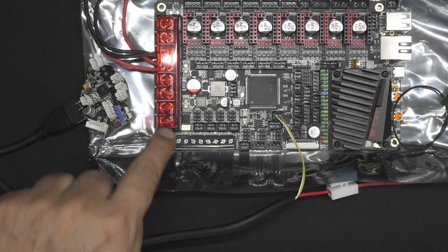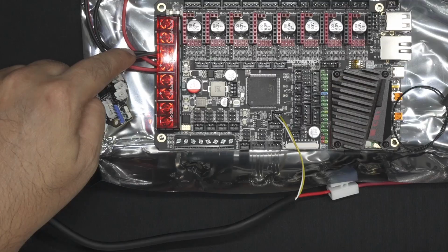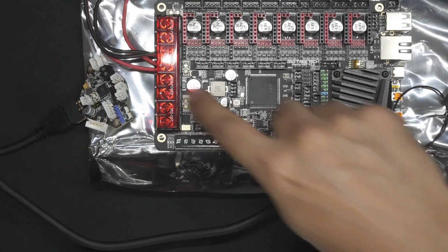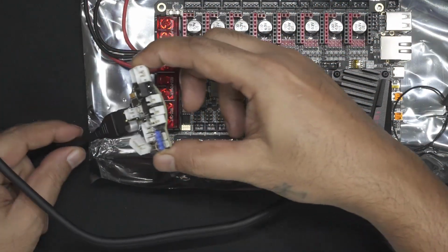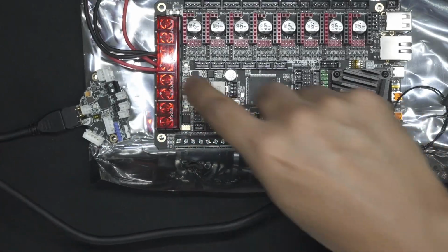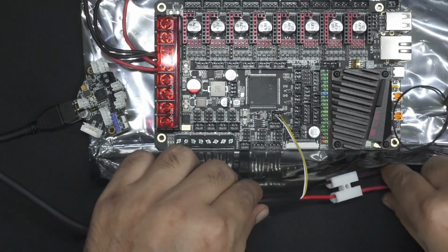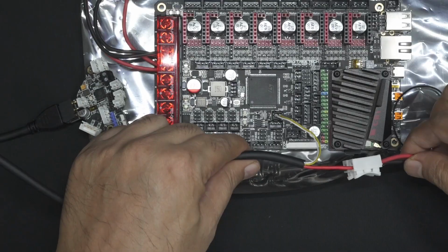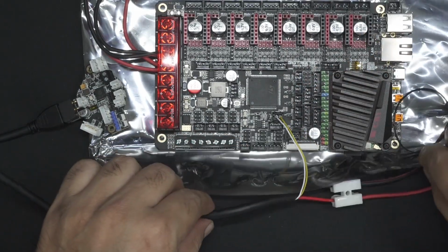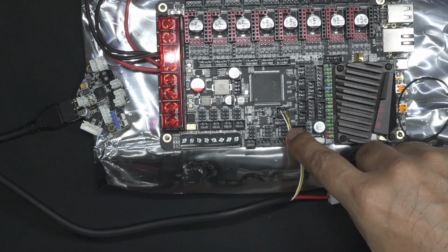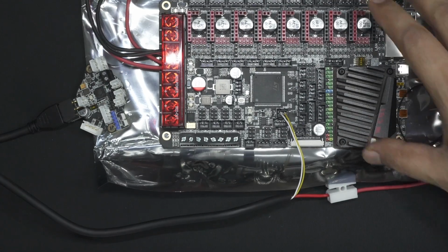So now the main board, I have connected the 24 volt power supply over here, and the same one I have looped back to the umbilical cord. So this cord is connected to the same power source that can be seen here. So it goes back to the same location, and also the CAN signal cable is connected. So now let's power on.